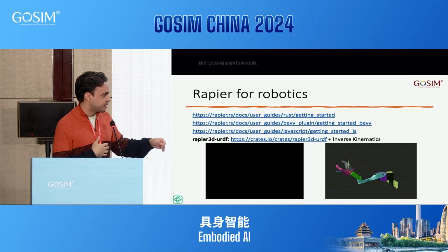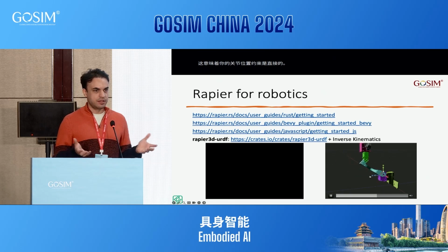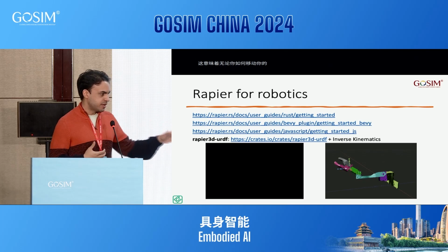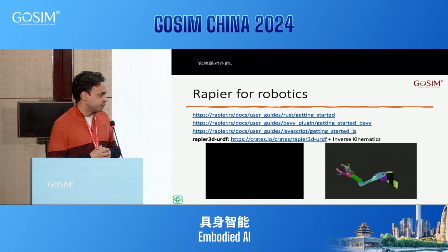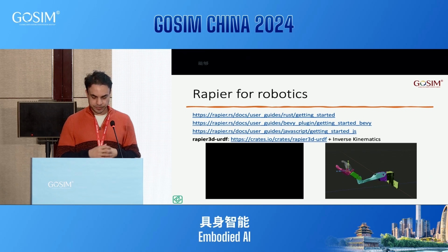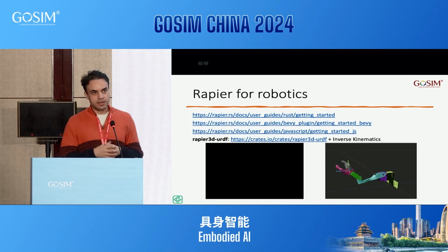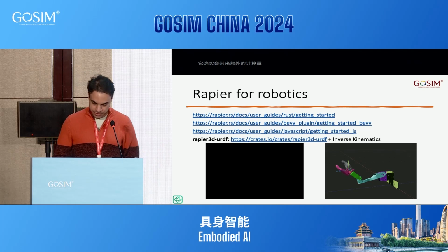And this is the case here, which means no matter how you move your object, you will never have any violation of the joint constraint. So it will always match what your actual robot is able to do with its arm. You don't have some weird drift between different links. It does come with extra computation time, and very sharp changes in velocities can be unstable, but in real life, you don't really have this.